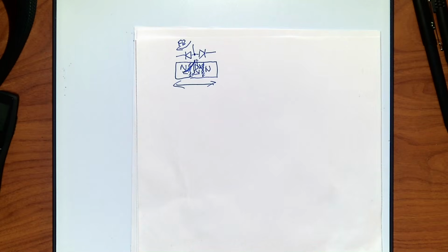When we realize we get that kind of beta value, everybody's gone through electronics, right? So typically that's like 99 or so. It's typically used as an input there. But as far as we're concerned, we have 2 orders of magnitude, plenty big, really easy to make this go on and off. Now, we're not going to care too much about straight amplification. We just want to flip things on and off. We're going to go kind of hard on that because we're going to use this as a switch.